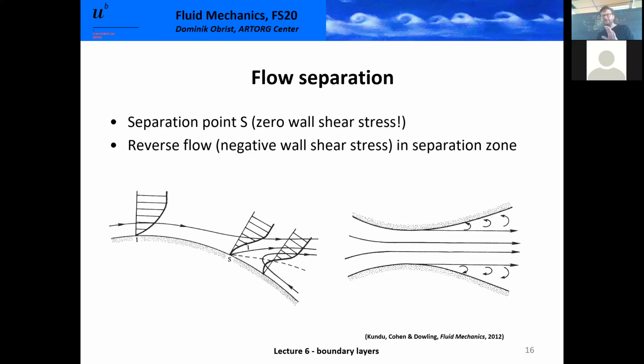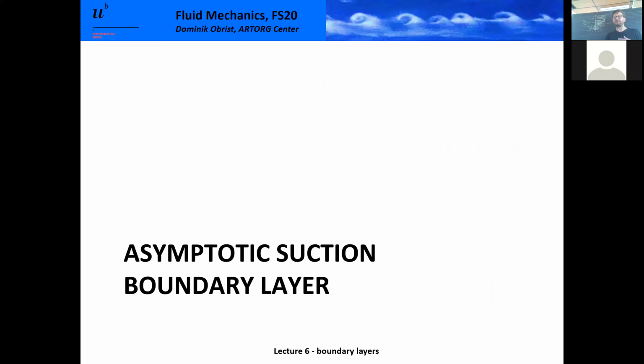Okay, so we have flow separation, and this is like a special case where the Falkner-Skan boundary layer goes beyond a certain critical point, and we get this reverse flow situation. Good, so this is the family of Falkner-Skan boundary layers. It allows us to describe, at least in 2 dimensions, most of the boundary layers on the surface of, let's say, a blunt object or an airfoil.